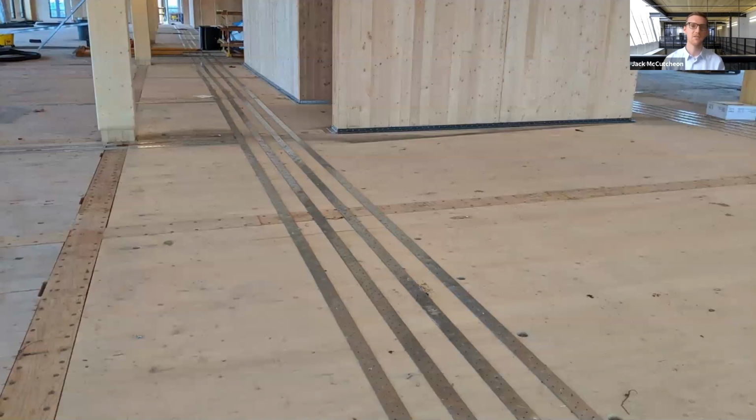And then the last photo here from the Catalyst project is just identifying some of the typical elements you might see with a CLT diaphragm. So if you can see my cursor, we have CLT floor panels, obviously, with plywood splines between each of the panels. Those transfer in-plane shear forces, as well as light gauge steel plate strapping connecting the panels.